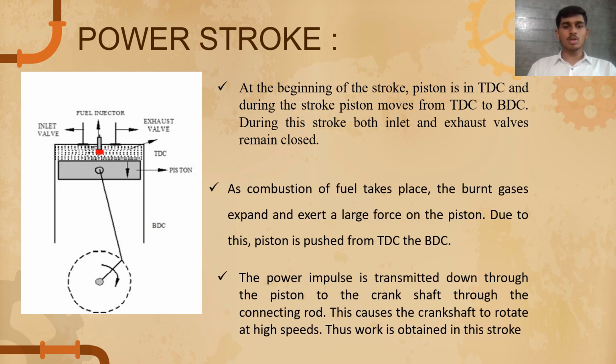So the power stroke. At the beginning of the stroke, the piston is at the top dead center, and during the stroke, the piston is moved from top dead center to bottom dead center. During the stroke, both the inlet and outlet valves are closed. When combustion of fuel takes place, the burned gases expand and exert a large force on the piston, and due to this, the piston is pushed from top dead center to bottom dead center.